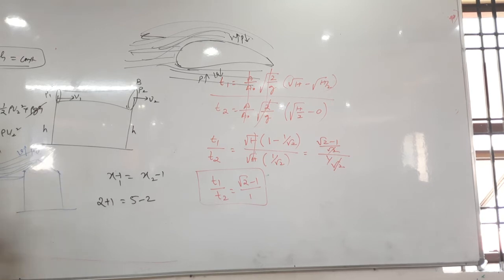Inside, is there any wind? There is no wind. Can I say that the velocity is almost zero? The velocity of the air inside is almost zero. Then it will have more pressure. So only due to this pressure difference, it will be lifted up. Rooftops will be lifted up. How will it be lifted up? Because outside, due to the outside wind, on the roof the velocity of the air will be more. Due to that more velocity the pressure will be less.